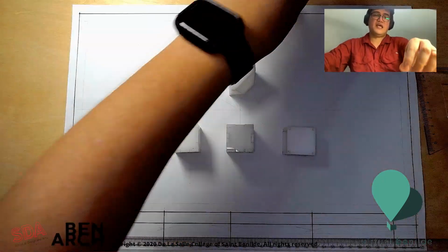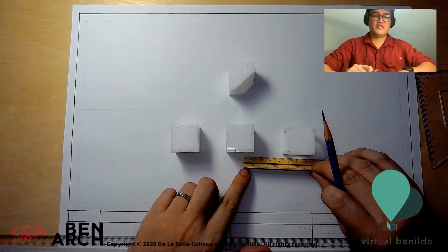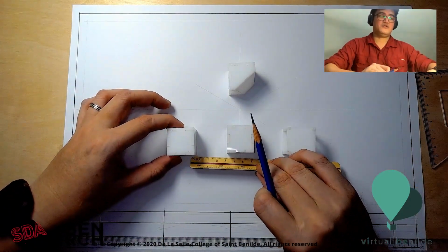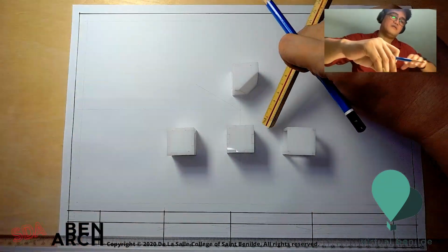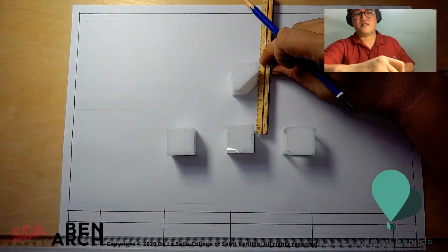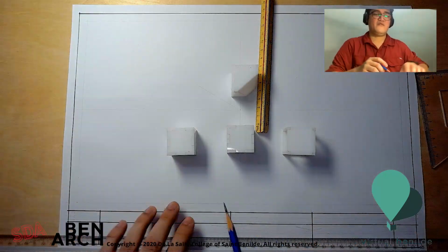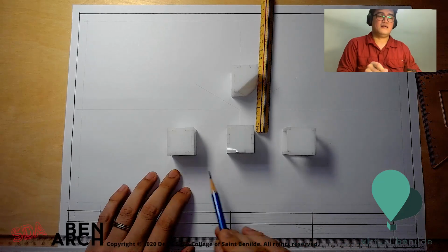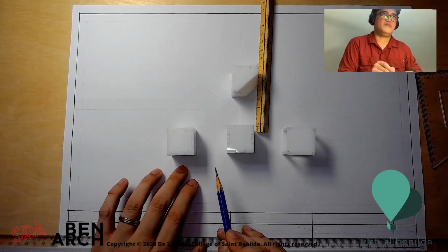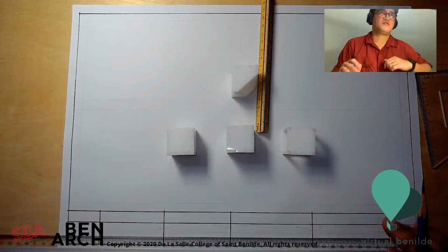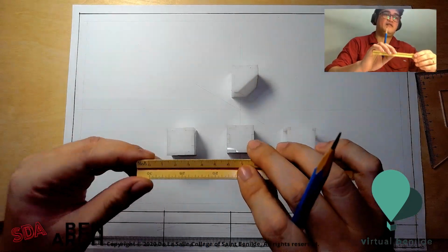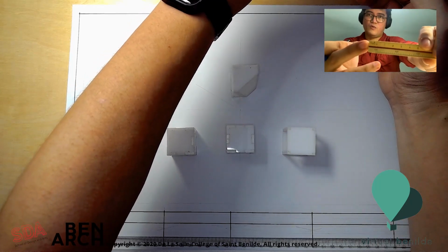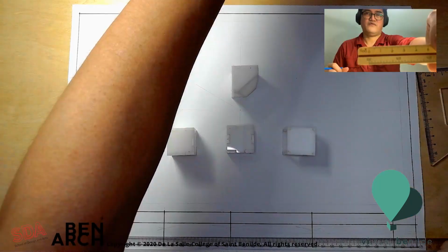So we're going to take probably a distance for each of these elevations to be roughly about 3 meters away each. And this one to be another 3 meters above. But then we have to consider also where the lettering is going to be. We're going to be titling these things. So this is going to be the left side elevation. So currently I'm using 1 to 100, which is big. So make sure that you are using your 1 to 100 at all times, if you're going to be using that.